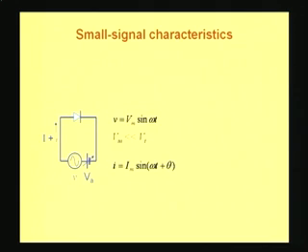So this is the biasing arrangement in which we measure the characteristics. You have a DC voltage applied across the diode. Although the circuit shows a forward bias, the DC voltage VA could as well be a reverse bias. Over and above this DC voltage is an AC voltage which is superimposed. So this is the AC voltage.